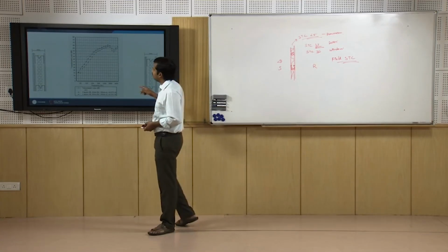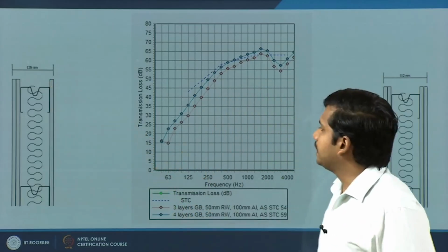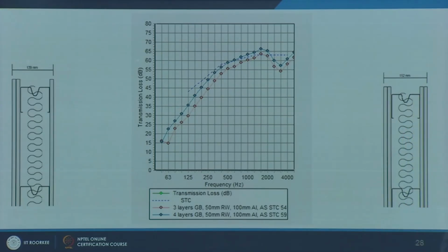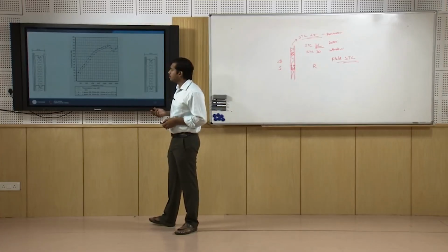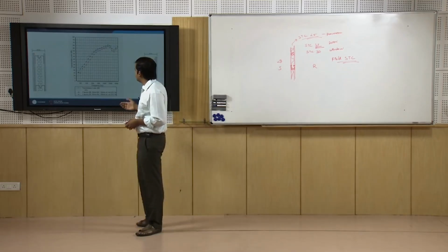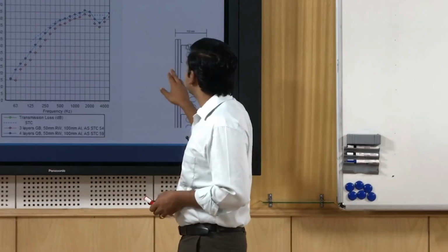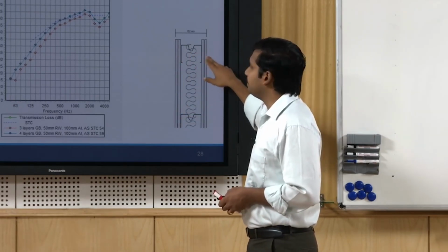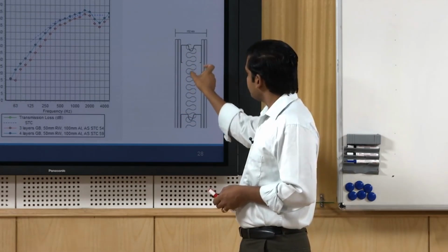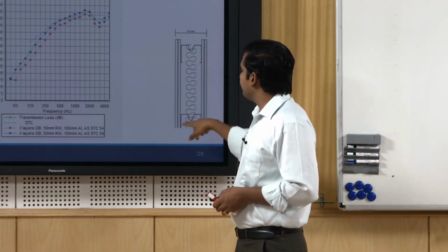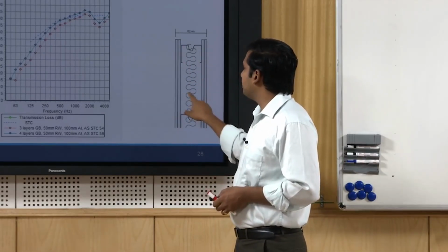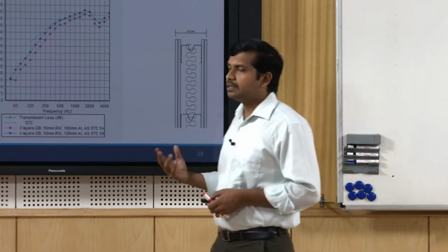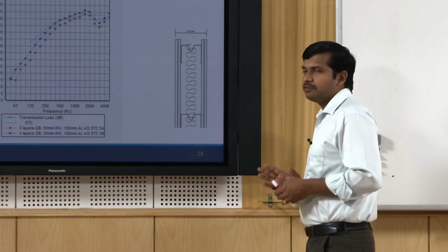Further to it, there are specific types of metal studs which are even better at isolating the sound transmission path, that is the airborne sound transmission path. So we will be able to achieve, for example, with 2 layers of gypsum on both sides with a specific type of acoustical stud with insulation of 50 mm and an air gap on both sides, up to 59 STC, which is really a good STC to achieve between the rooms.